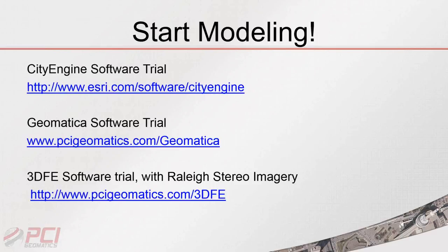On the CityEngine side, how it operates is we have folders of buckets. You can use a bucket of textures that you pre-create or ones that are existing in the data to texture the buildings based on a usage type, or generically texture them all with similar textures based on their variables. You can customize and code this with what we call CGA, or shape grammar, the programming language that CityEngine uses. In doing that, it basically says, okay, the building's this tall, the usage is this, or some other information. Let's give it this generic texture.